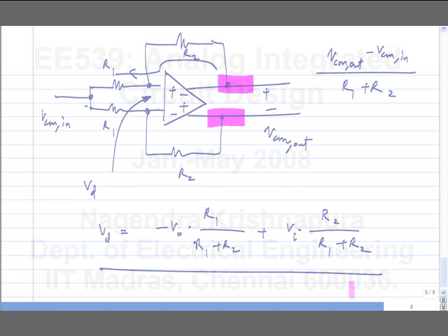Typically that's considered to be the internal business of the op-amp, because the user is interested in the signal processing chain, how the signal propagates through the chain. So you want to make a differential amplifier, that's why you go and do this. You're not interested in also stabilizing the common mode loop so that the op-amp functions. So when you make a differential op-amp, you need to provide the common mode feedback internally, so that externally you can think of applying differential feedback and using it in whatever application you want.